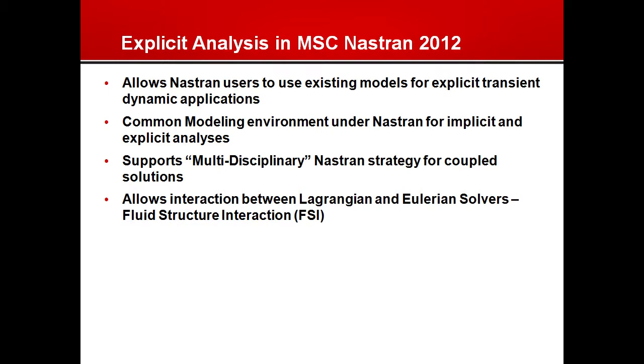So this explicit analysis allows Nastran users to use existing models. We can bring in existing models, and you'll see me do this in the upcoming demonstration. So you've already got models there at some point. Common modeling environment: we can use familiar preprocessors and post-processors. If you're familiar with Patran or SimExpert, those are our pre- and post-processors. And we use one; we don't have to have multiple different environments and codes to pre- and post-process these explicit simulations. We also have what we'll call multidisciplinary support for explicit.